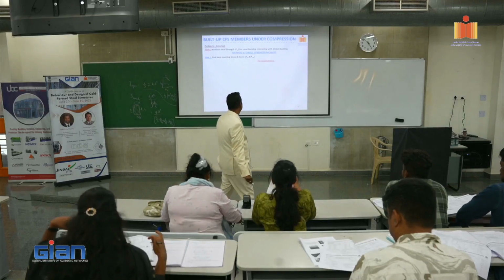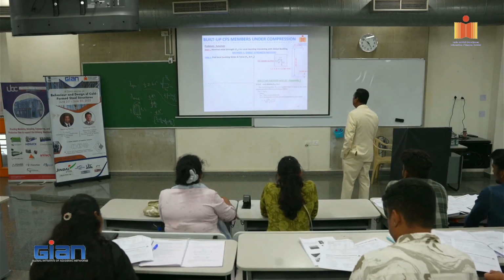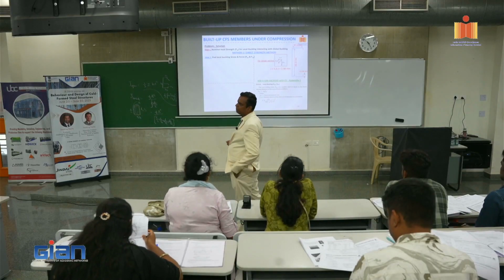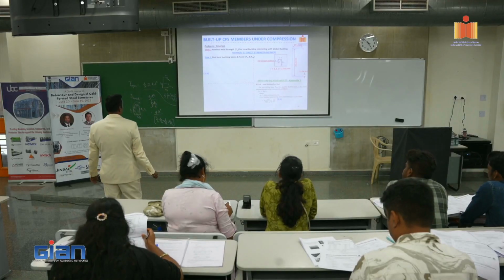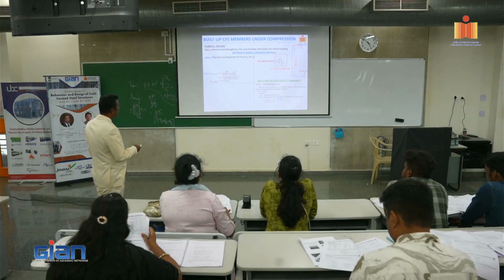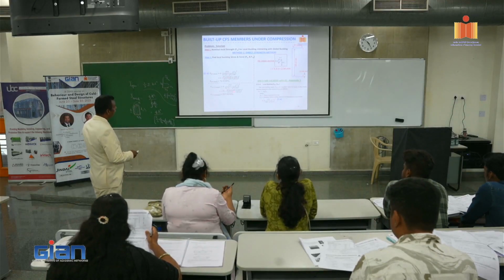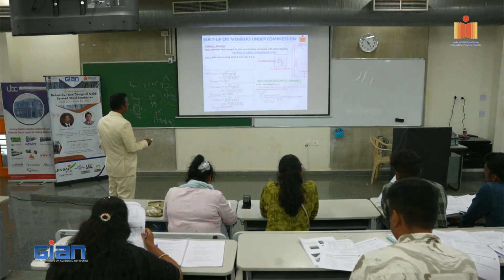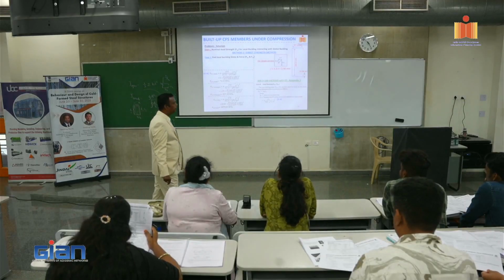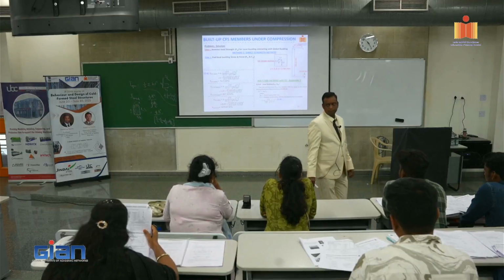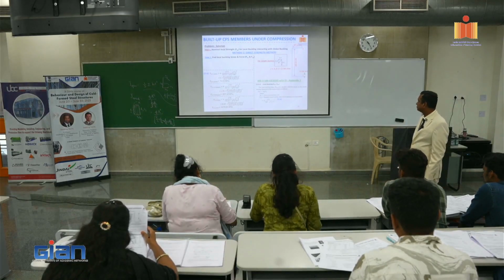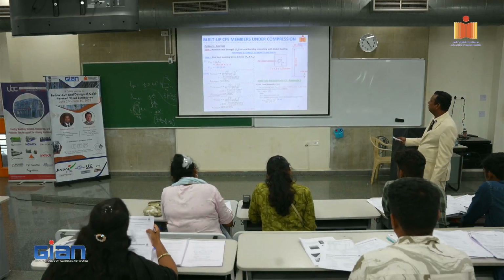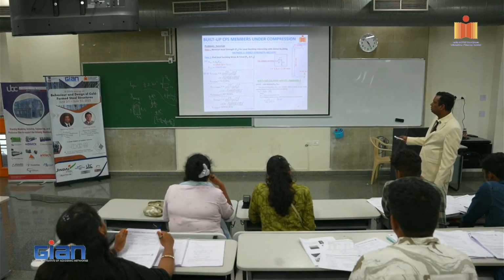So in the direct strength method, for a single section, we have all these things. Local buckling is given as k into pi square E divided by 12 into 1 minus nu square into b by t the whole square. When it comes to the top, it becomes t by w the whole square. For the web, we know that k is 4, so the value is 76.15. For the flange, we know that k is 2.29, you get 357. For the lip, it is 0.43. So the lowest one is 76.15. So the web buckles first before the flanges and the lip. That's the meaning of this. So FCRL is 76.15. Now you multiply this one with the AG, you get PCRL equal to 109.29.